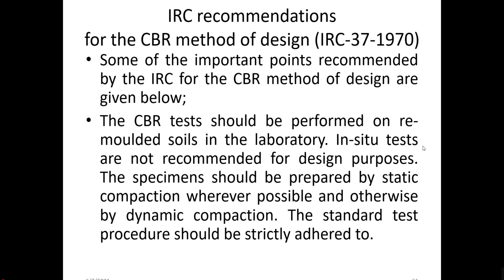In situ tests are not recommended for design purposes. In situ means at the practical site condition, then and there itself. If you try to measure the CBR test there, then it is not permitted.